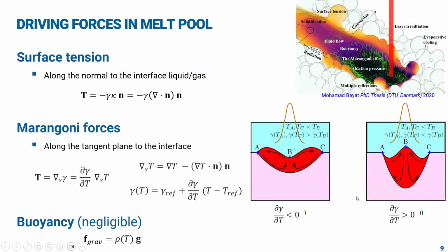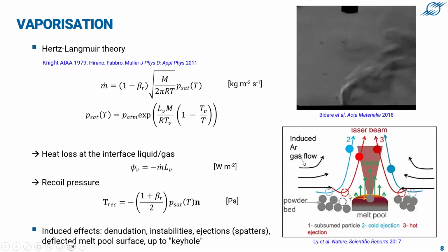And you have this ascending movement of argon. And because of that, you can have instabilities in the powder bed. For instance, particles that will be entrained in the flow of argon that can be melted when passing through the laser beam and being ejected on the part that is on the deposition that is in course.